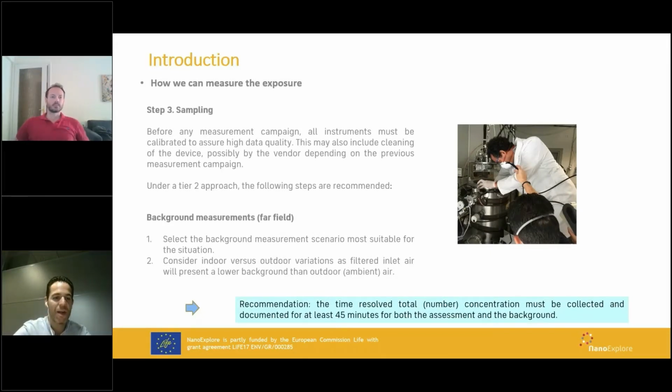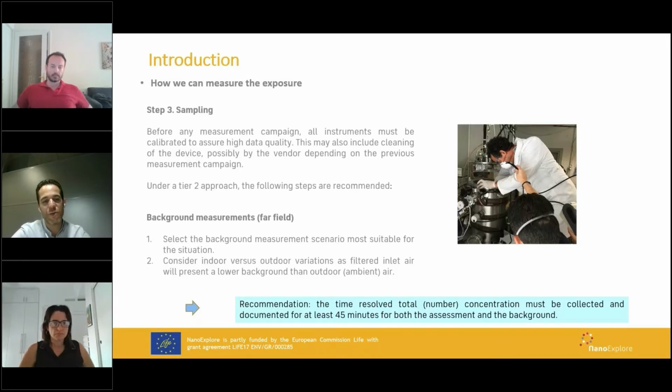During the sampling, normally we measure, for example, 1 hour of the background levels. Background levels could be the levels of materials when the activity is closed, so there are no people working in the labs, or no people working in the company, or before the processes. Sometimes, for example, we measure 1 hour or 2 hours before the process starts, just to have an idea of the potential levels of exposure in the background noise. Then during the activity, we measure with this kind of devices.